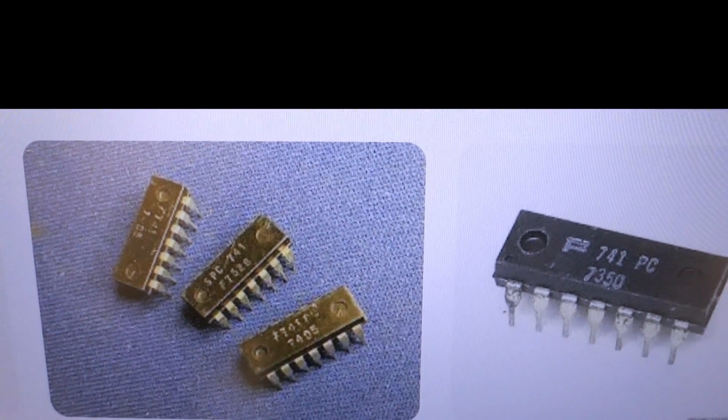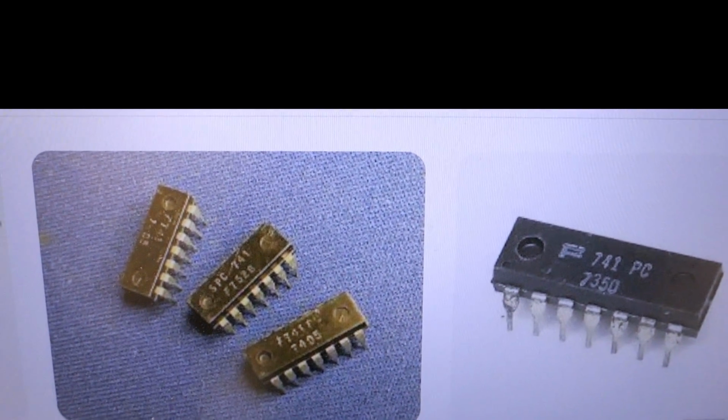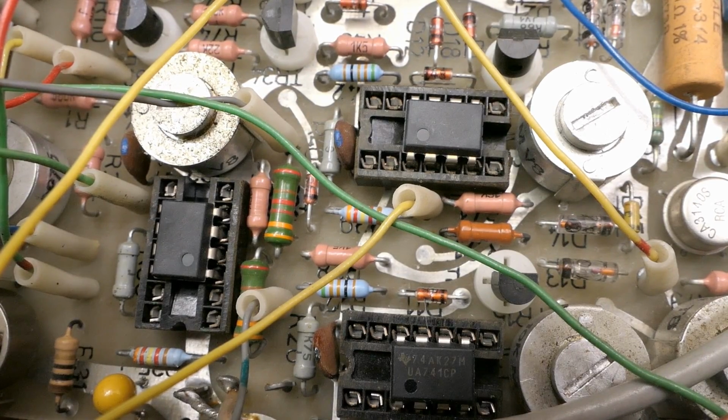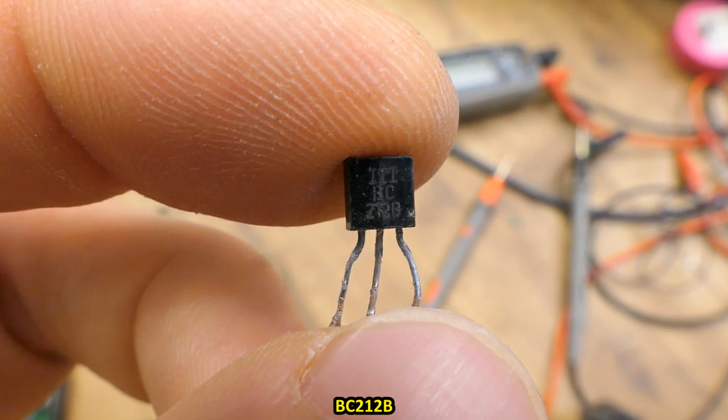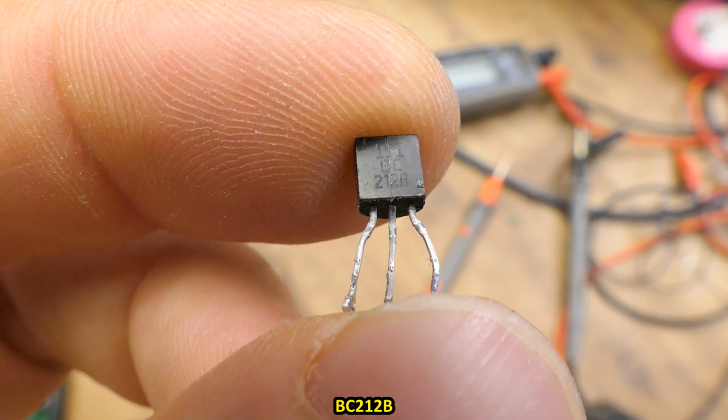And by the way, it seems that very old 741 op-amps actually were 14 pins and a lot of pins unused. That's the reason for the 14 pin sockets. Here's the transistor desoldered, and measuring it using the multimeter outside of the board shows exactly the same thing.